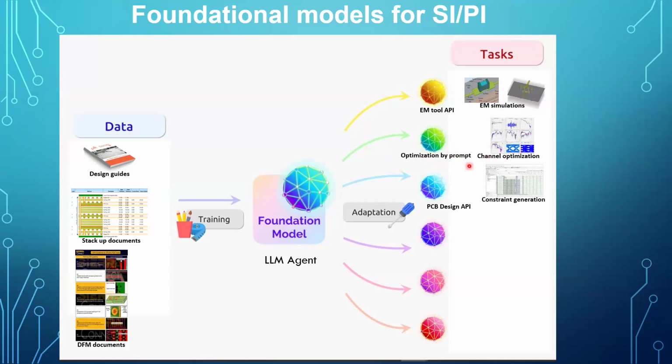What's the next step? You can use this desirable result and tap into, for example, board routing, which is what we call the constraint manager, right? We can feed those desirable geometries, maximum length, minimum spacing, everything that we simulate and optimize, and you can easily generate the design constraint file. That's a pretty straightforward exercise, right? And obviously the last step is you can use the API to do the auto-routing.